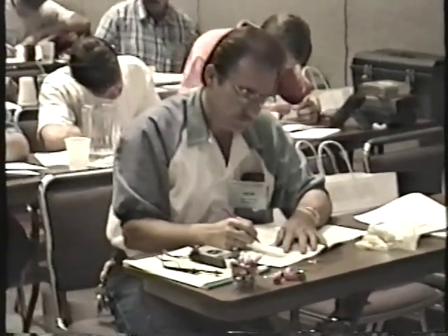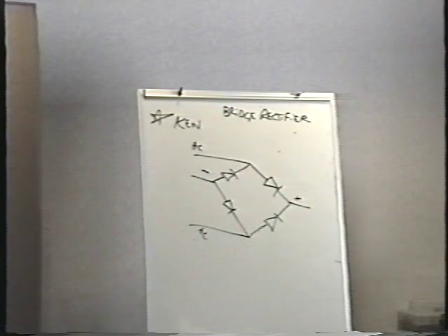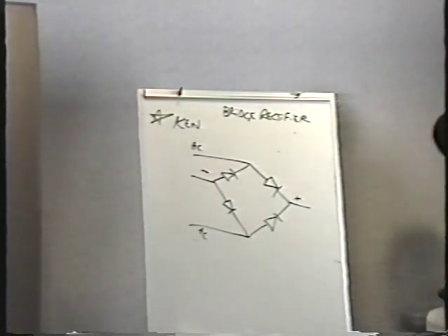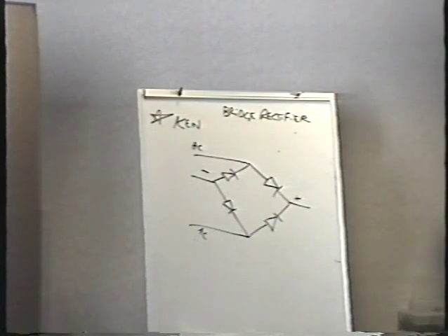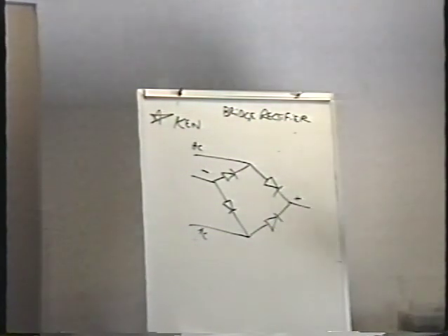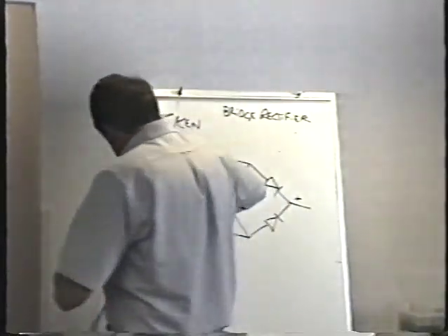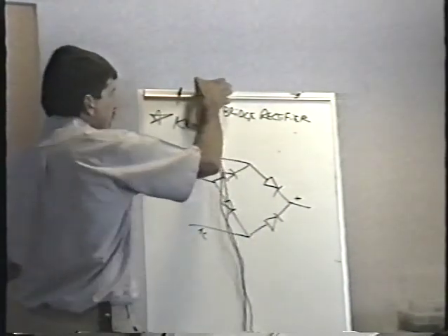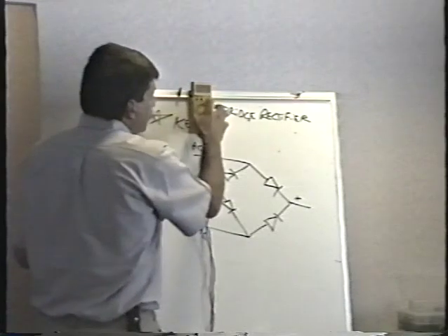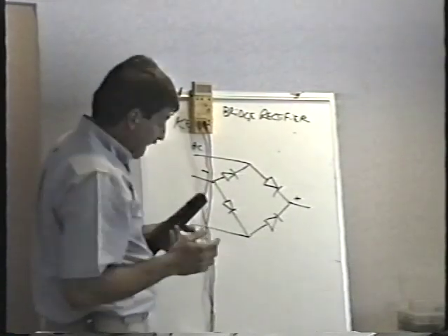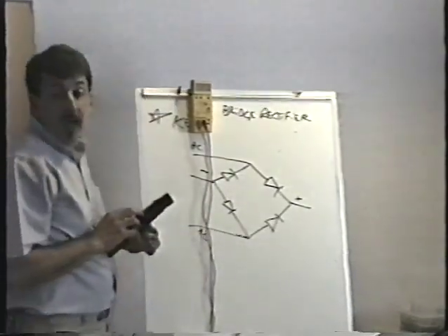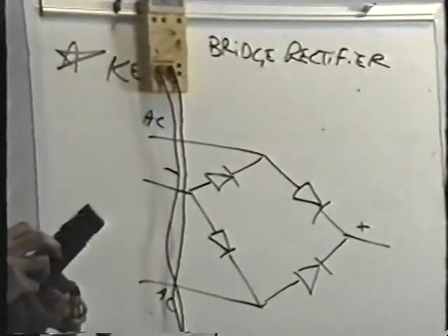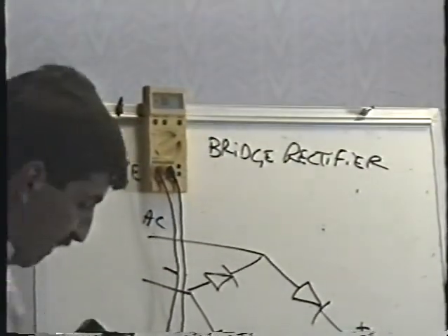But it's very easy to test the bridge rectifier to see if it's good or bad, because all you have to do is test it as if it is 4 individual diodes. And again, you're going to use the diode test setting on your meter.